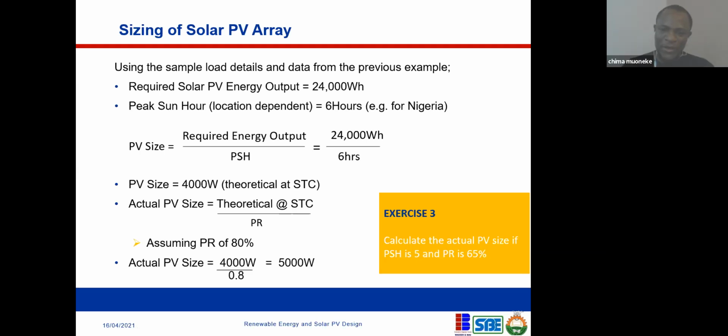I'm coming to the current when I discuss the charge controller, but about the voltage, it all depends on the voltage rating. These PV systems have voltage ratings. When you look at the data sheet, you will see the output voltage, VOC, open circuit voltage, on those PV systems. So it depends on what you're connecting to. What voltage of battery do you want to charge? Okay. So that will determine how you'll be able to connect them.